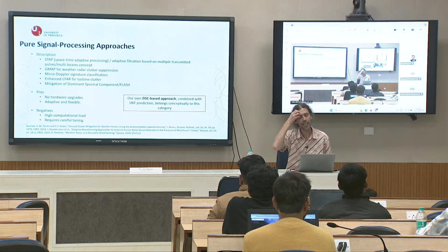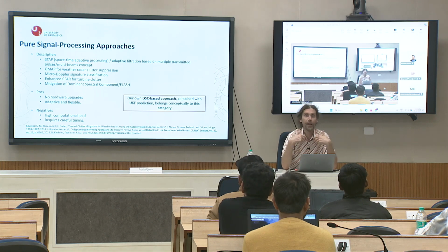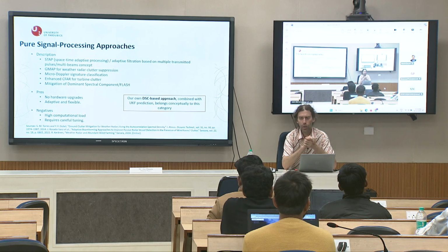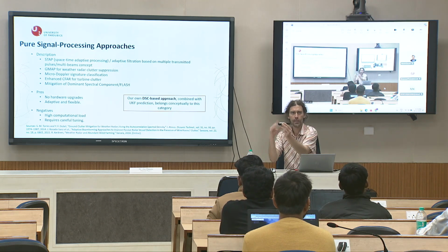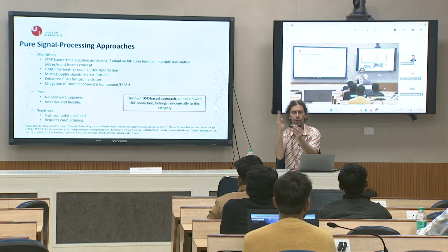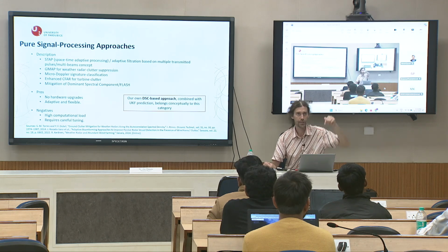And this jittering you can identify, and it is special for wind turbines. And if I can identify it, I can play with it, I can mitigate it and so on. So this is microdoppler. You can have microdoppler also in a UAV. With a UAV, the motion shifts the frequency, but you have 4 blades, like a quadrocopter, you have 4 blades.